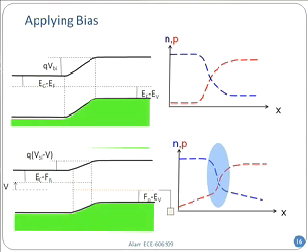However, as soon as you apply a forward bias, let's say by the amount V, the product np will not remain equal to n_i squared anymore. That is what I have shown in the bottom right figure: the carrier concentration is no longer the same, and in the junction region especially, it has been modified quite a bit. You can see the linearly drooping region on the blue curve. That's the diffusion. Remember the triangular region? That's why I'm trying to show it there.